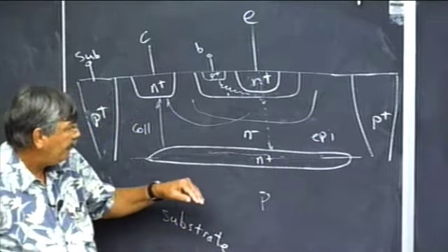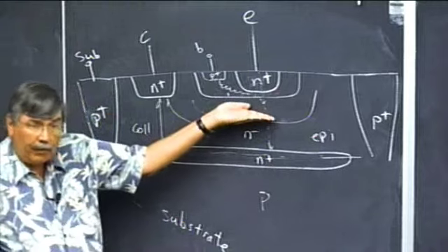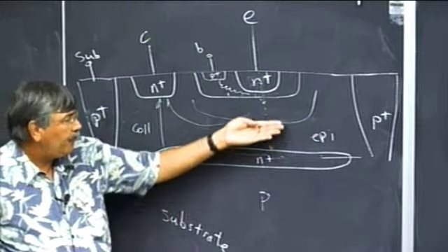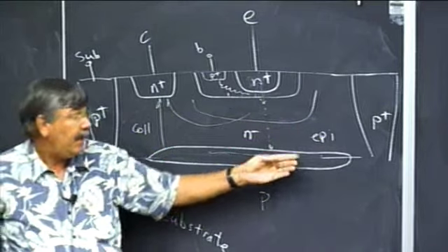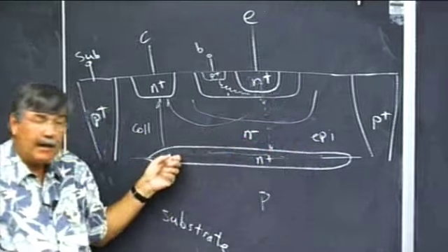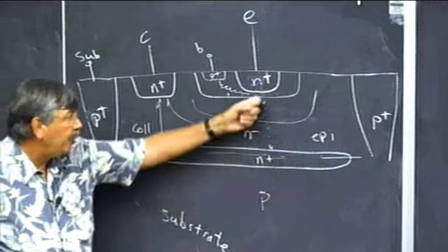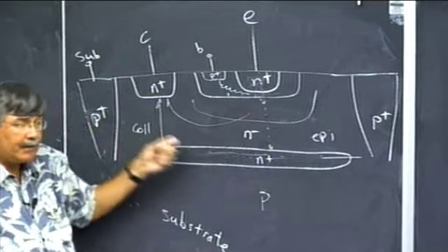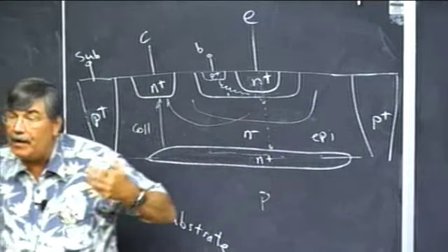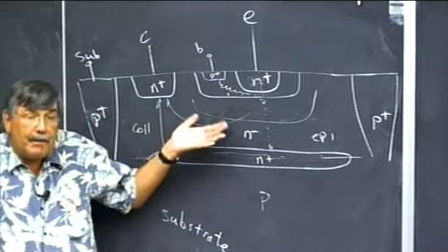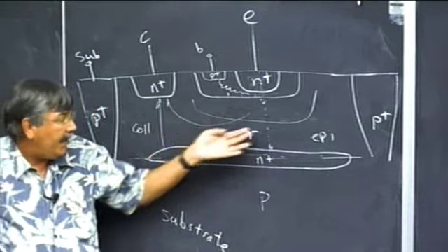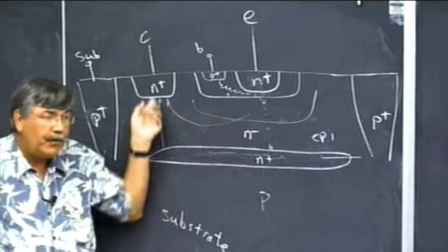And so we probably would have scooted this up closer. We don't want it too close. We want it just far enough so that the depletion layer will never bang into it. And then this buried layer reduces the total resistance of the main signal path, main current path here. So we have a trade-off between the breakdown voltage, which we'd like to be reasonably large, and the resistance that's in series with the collector.